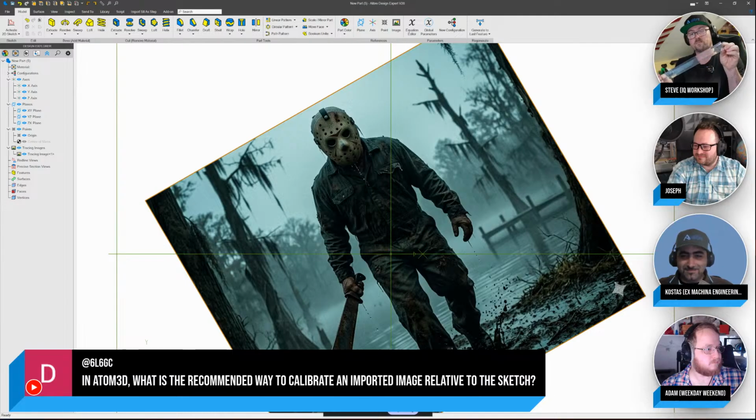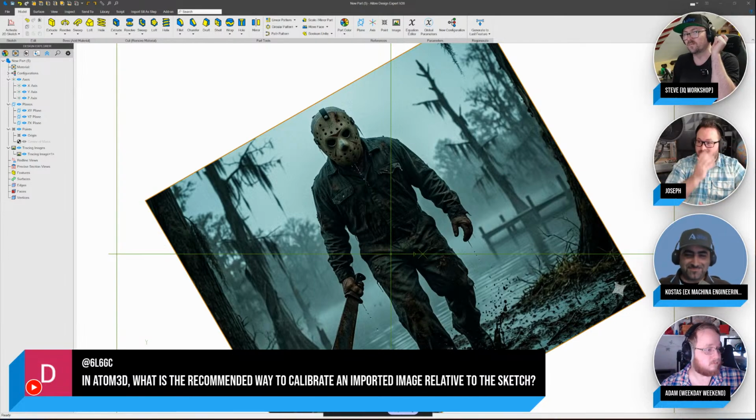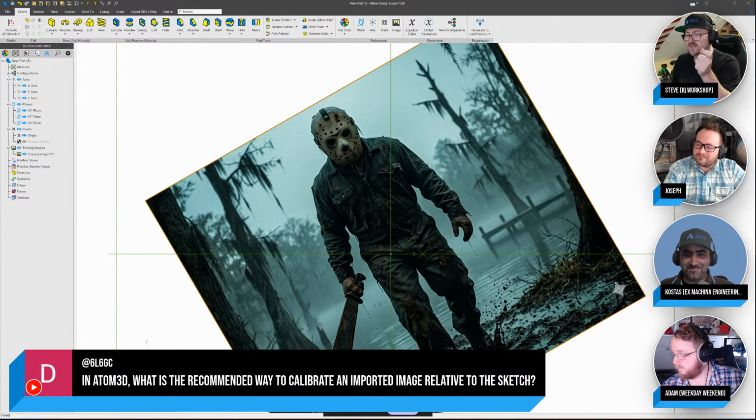And the larger the scale that I use, so this is a 30 centimeter ruler, if I use all of it, the amount of error is reduced the further you go. You know, if you only measured like 1 centimeter or 10 millimeters versus 100 millimeters versus 300 millimeters, the factor of your error reduces. So that's the first tip.